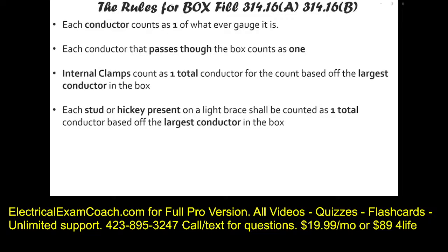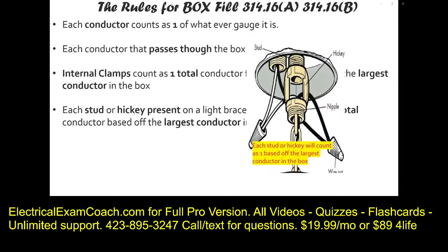Now, these are really old words, probably from the 30s if I had to imagine, but they still use them on examinations today. And this is what we're talking about. Imagine that we're hanging a chandelier. This we would call the stud or the nipple. Or, this would be the nipple. But they're calling this the stud and this a hickey. And they still use this terminology on exams today, so you definitely need to understand. In this scenario, in this picture, the stud would count as 1 of whatever gauge was in the box that was the largest, and the hickey would count as 1 of whatever gauge was in the box that is the largest. And we're going to do lots of practice, so don't worry about it.